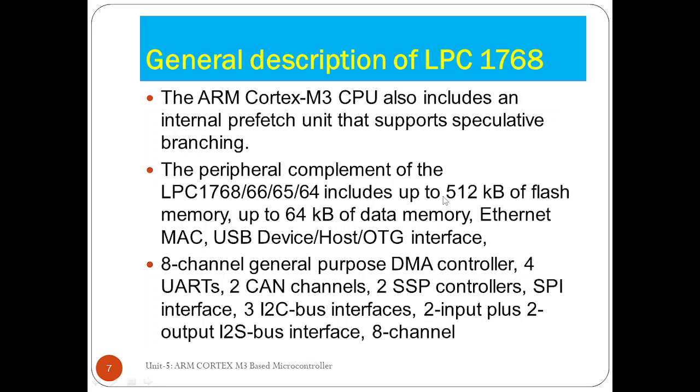The peripheral components are 512 KB flash, 64 KB data memory, Ethernet, and USB; 8 channel is available. These are the specifications of LPC 2148. In some applications we need UART, the CAN protocol for communication, SSP protocol, SPI interface, and I2C bus.